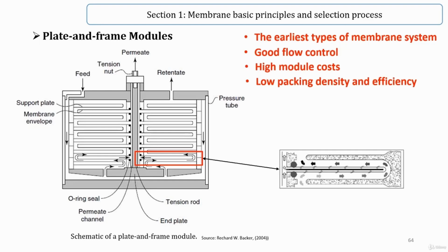Membrane, feed spacers, and product spacers are layered together between two end plates. The feed mixture is forced across the surface of the membrane. Permeate enters the membrane envelope, enters the permeate channel, and is collected through the central permeate connection channel.